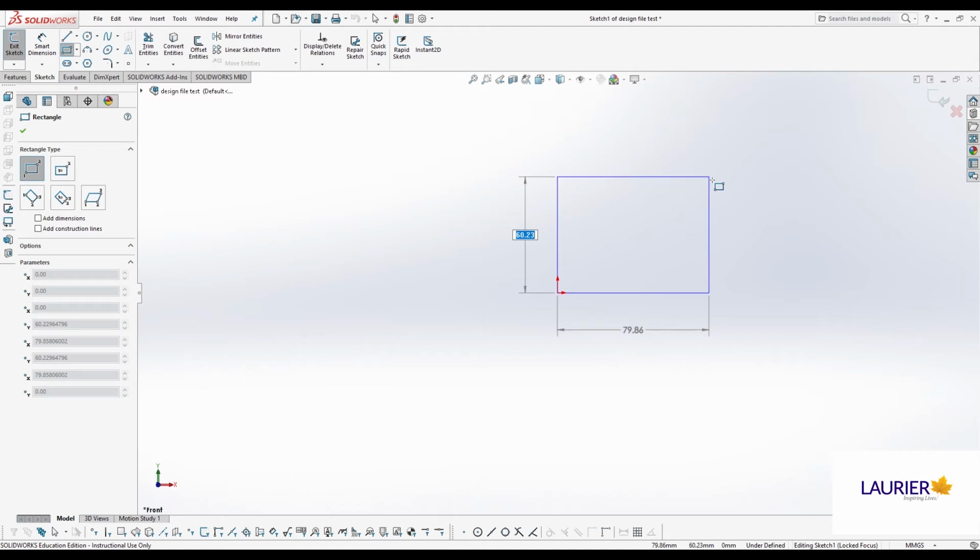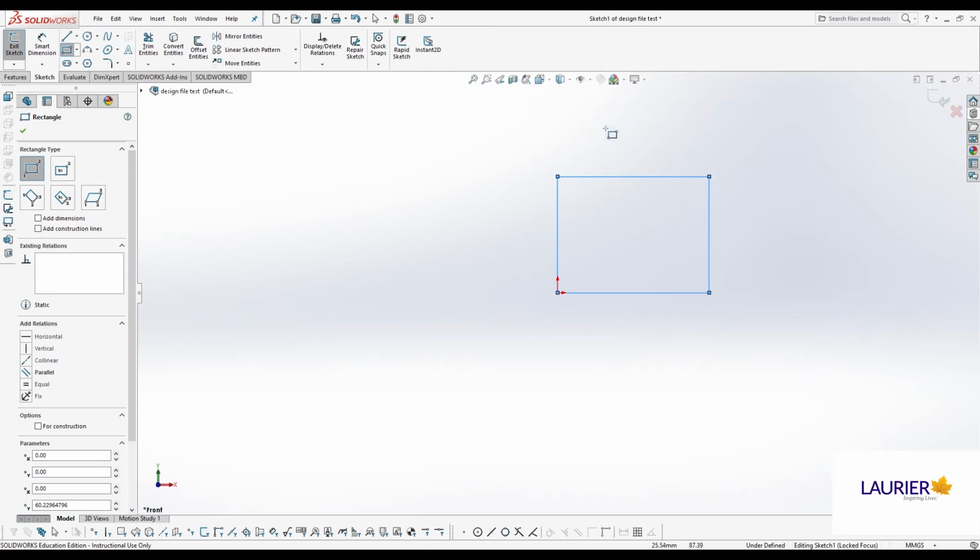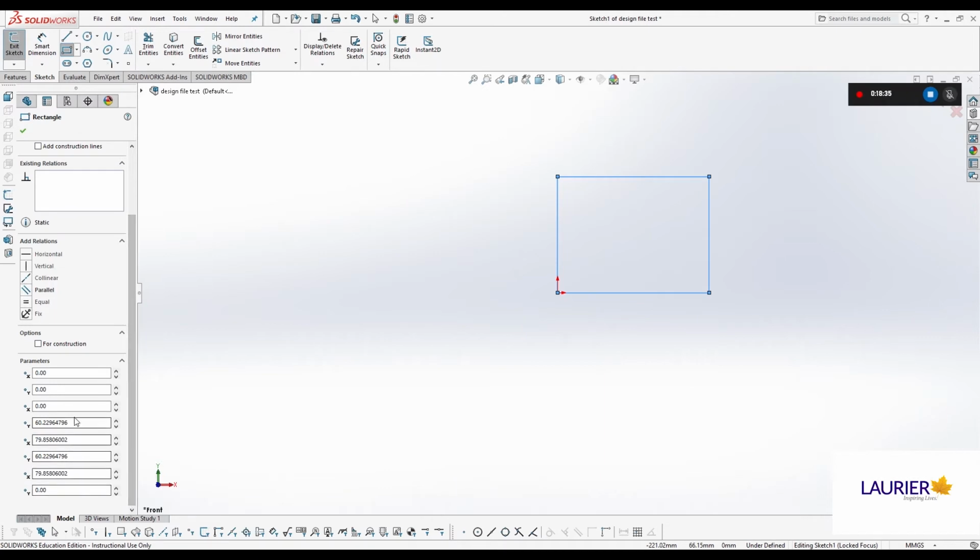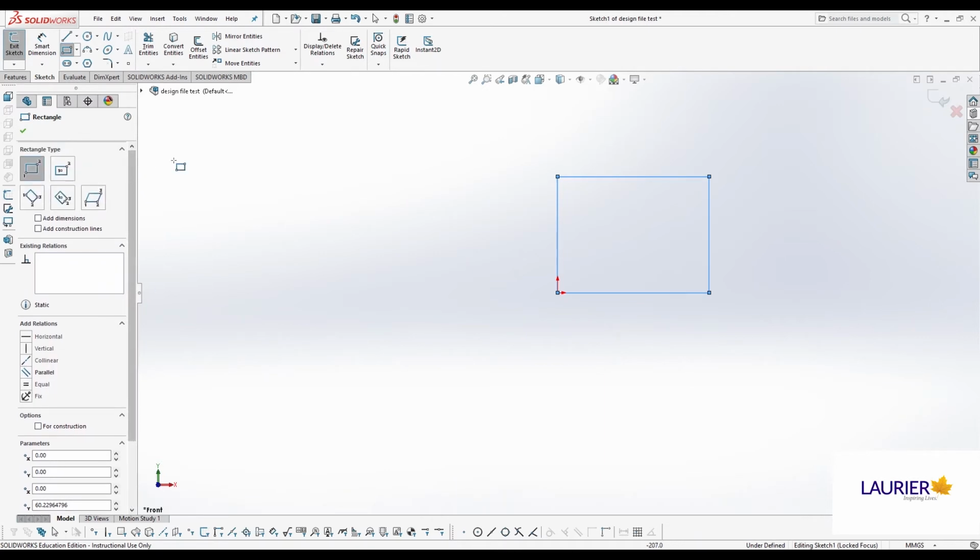So the bad news is you can't get it to exactly those numbers. The good news is it doesn't matter. Because we have these driving dimensions, we can sketch just like we do on the whiteboard and make kind of a rough sketch that's not really in proportion, and we slap on dimensions. On the whiteboard, we use it as a reference. In the CAD with driving dimensions, when we apply dimensions to our rough drawing, the CAD actually forces whatever line we dimensioned to be the size that we put in.